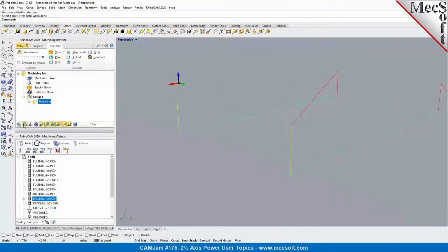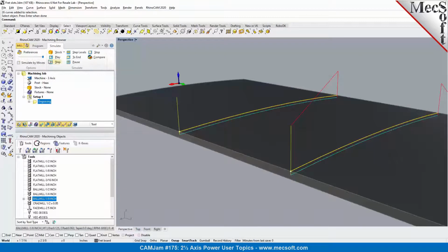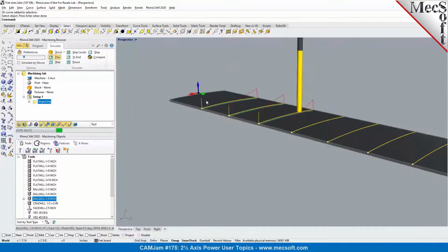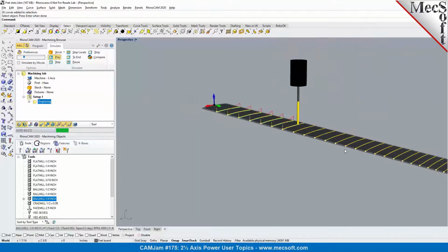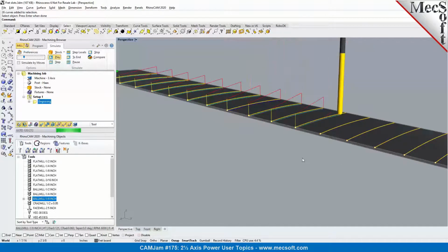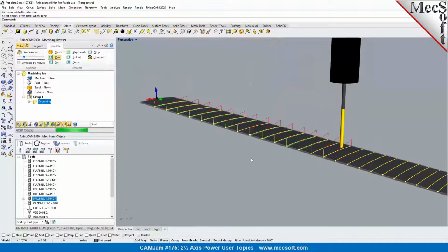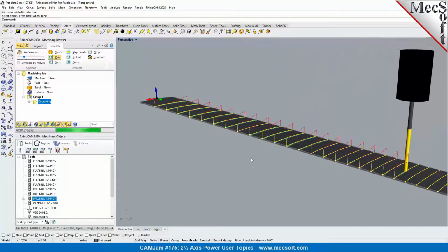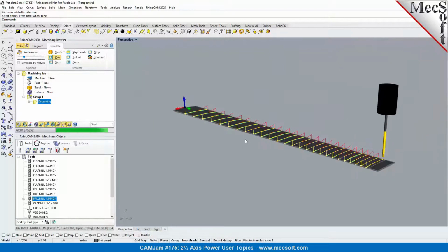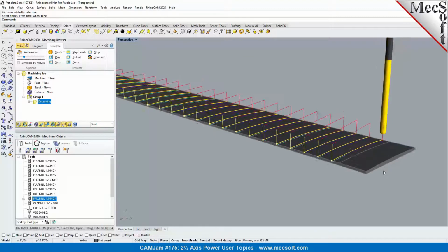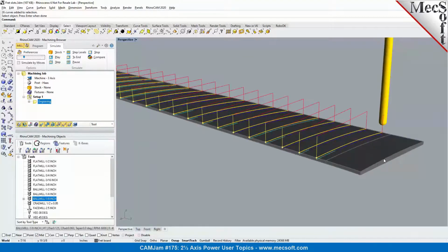So I'm going to run a toolpath animation in here, as I've not defined a stock for it, but you'll see it here. So it follows the 3D curve. So just to summarize, engraving can be used for programming open and closed curves. These curves could be 2D or 3D. You could be even selecting surface edges, not necessarily have to be curves. You could even pick surface edges from your solid surface geometry as your part region for engraving.